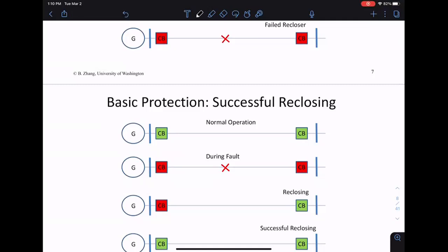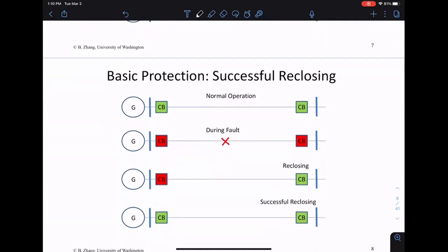We'll see a little bit more of these protection issues when we talk about solar. But for wind, the way we solve the protection issue is we tell the wind turbine, basically, to stay online. The reason you have to stay online is you're waiting for the other breakers to do this kind of dance. If they're successful, then by staying online, you can recover the entire system.